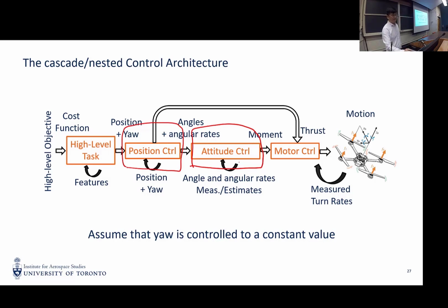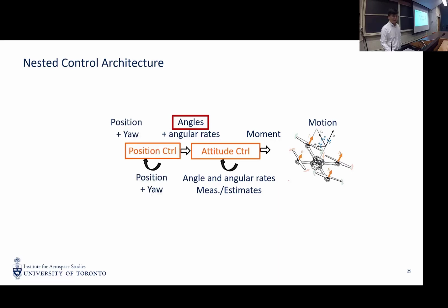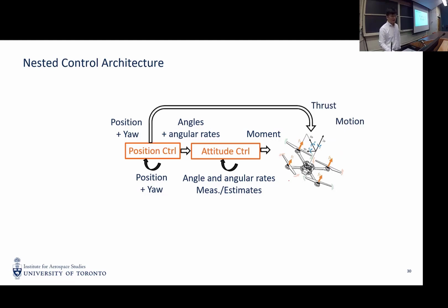And if we obtain the attitude controller, then by using the rotor thrust mixing algorithm we introduced last time, we can get the thrust on each individual rotor. Good. So these are the detailed steps. You start with attitude control, then you design a positional channel, and after that, based on the position channel, you can design some kind of higher level mission module.